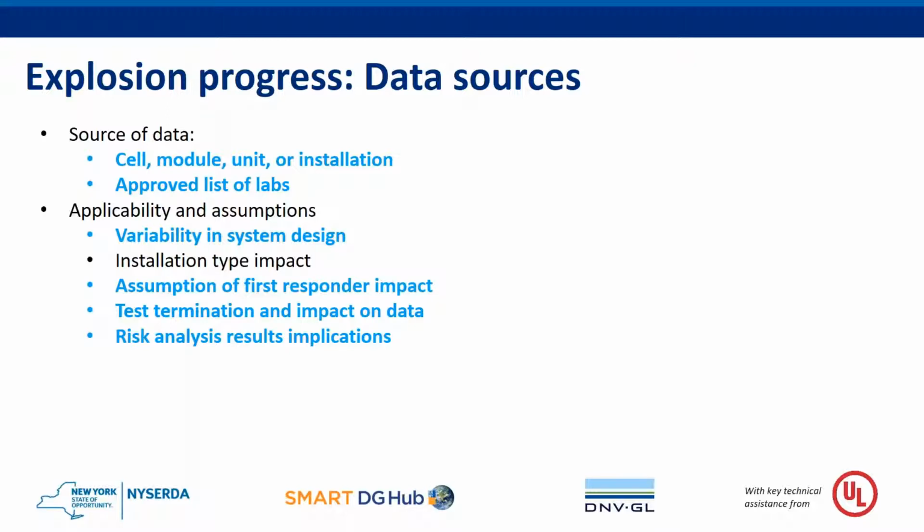The initial standard that was proposed is UL 1973, but there's still some discussion ongoing with UL to help identify another standard that zones in on the capability to do calorimetry, which is a key part of the UL 9540A standard. But the initial thought was if you're certified to conduct UL 1973 tests, that you can conduct UL 9540A tests, of course, given that you can do it safely and in line with the testing practices. But as I noted, we're working on defining if there's an additional standard that we can layer on top of that to ensure the best results.